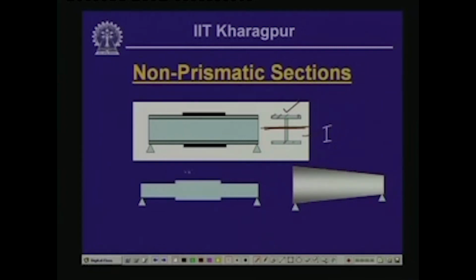Now, if the beam is simply supported and subjected to different kinds of loading, either concentrated or distributed load, the maximum bending moment occurs at the center of the span. To enhance the strength of the beam, many times in the central region we add some additional material, so that the moment of inertia can be enhanced further. That means, on top of these we can add a plate on either side, so that the moment of inertia of the cross section in this region is enhanced.